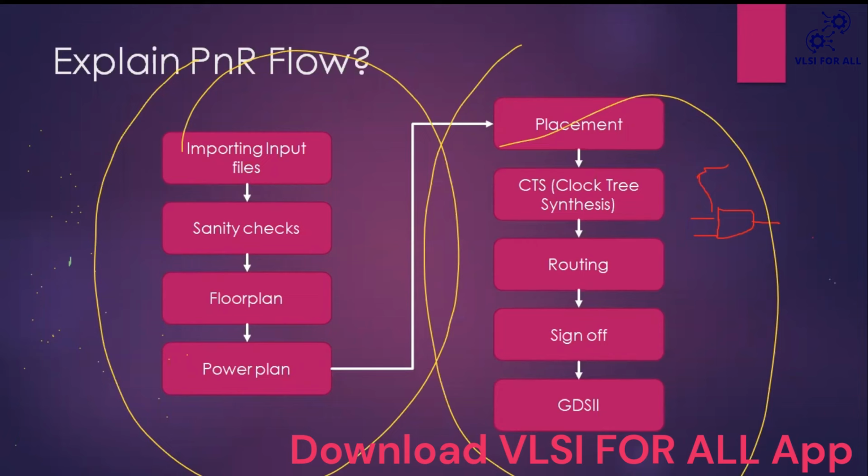After clock tree synthesis only, we start fixing hold violations, because after CTS only the original hold violations will come into the picture. Before CTS, hold violations we cannot trust. After CTS only we'll trust the hold violations and start to fix them.